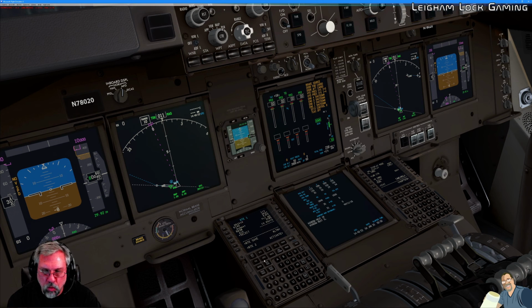Where we were just a moment ago, right, we were looking at our departure. We had picked our runway 30. We're using our SID of Jacoby 3 with a transition waypoint of Agard. When we go back to route, it brings us back to page 1 of 2. We're going to go to next page, and we can see that SID of Jacoby 3 with the Agard transition already listed in our route.